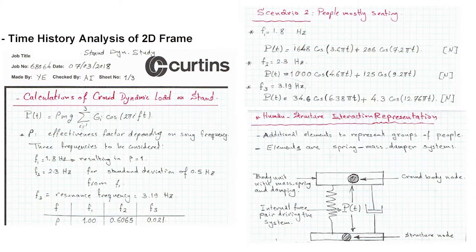Most of the structures existing now have a frequency of about 3.5 Hz, which requires going through the complex method of analysis, which is applying the actual load as periodic loads to the structure, and then assessing the maximum response of the building, and then comparing that with the acceptable limits from previous experience.